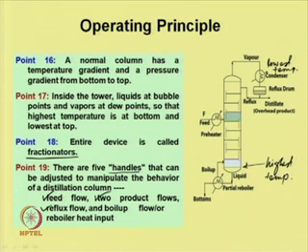Reflux flow, the reflux ratio we can change, and boil off flow or the reboiler heat input. The boil off is what comes out from the reboiler. So, this flow we can control. These are the 5 things which we can control to manipulate the behavior of a distillation column.